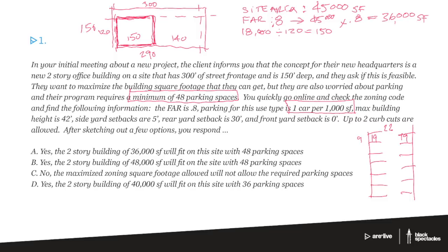And so when we add that all up all the way across, we're going to get somewhere between 60 to 62, maybe 64 feet, depending on how big a drive aisle we want. So if we have 2 parking lots, we can absolutely fit them right there next to each other, 2 curb cuts into the street, and then connecting across.